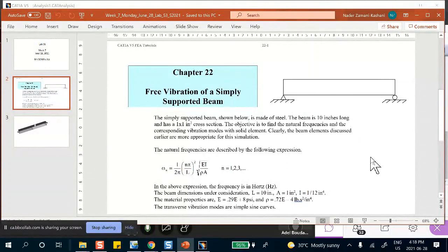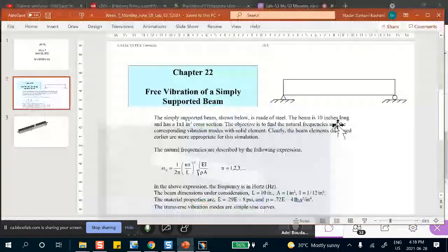In fact, the three-point bending test that you do in a lab, if you want, for concrete or for I-beam, etc., they don't have this configuration. They take a sample, put it on two cylindrical surfaces here, cylindrical rods, basically it becomes your roller, and then load it. Okay, but when you did problems in deformable bodies, in mechanics, etc., you assumed this was a pin. Okay, so I'm going to do the same thing, except that,